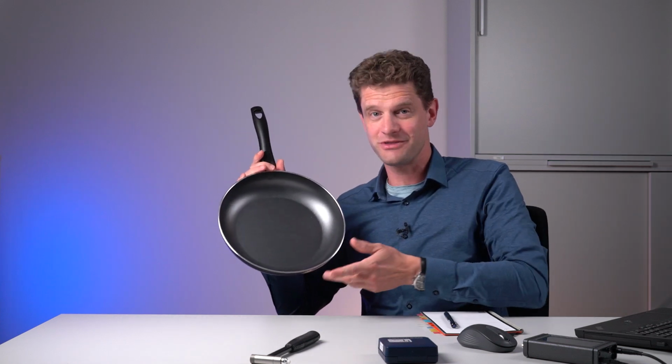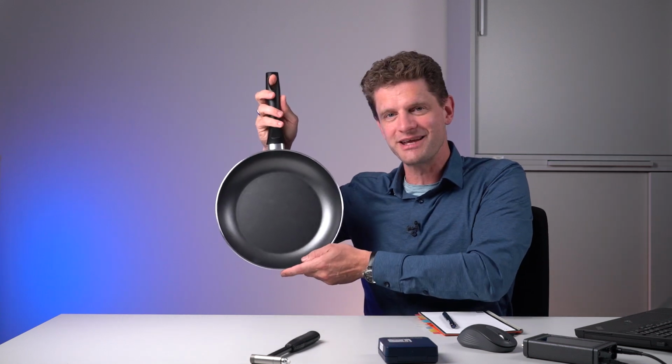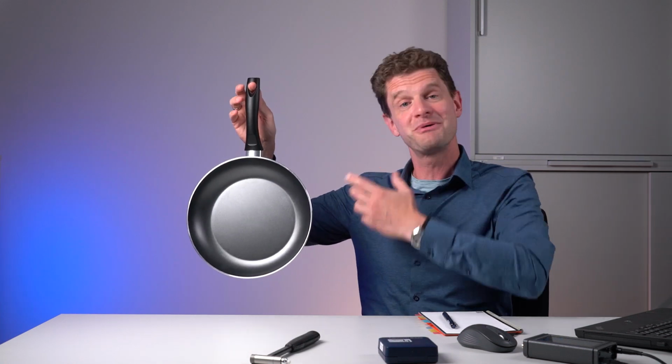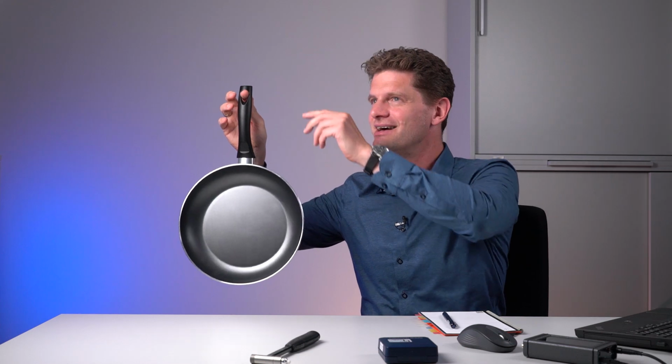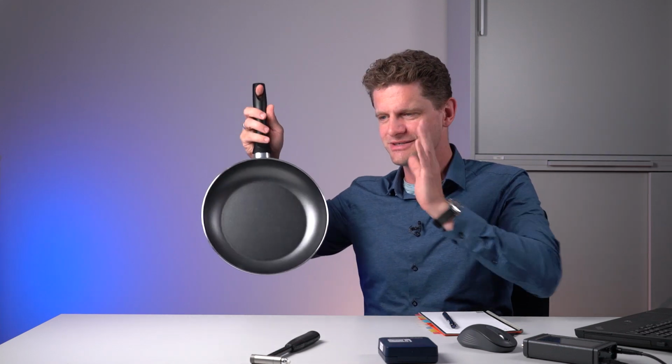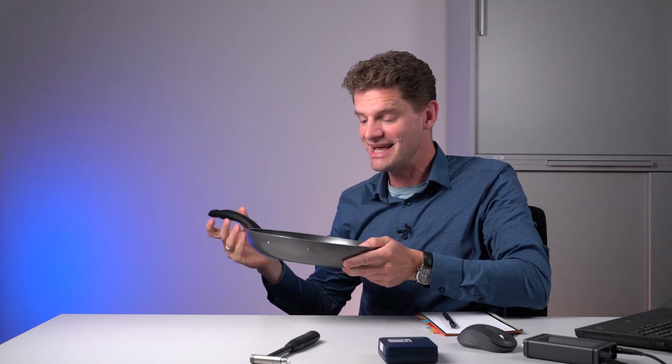Now we will measure an FRF of this pan, a frequency response function of this object. And as we learned in the 3 videos before, the easiest way to get the FRF is to put an impact on it. So I just put an impact on the pan. And the response is boom. There's several tones in there. It's easier to hear if I impact it here. Boom. So some tones are in there, and that is the eigenvalue, the eigenfrequency, the modes in this pan.